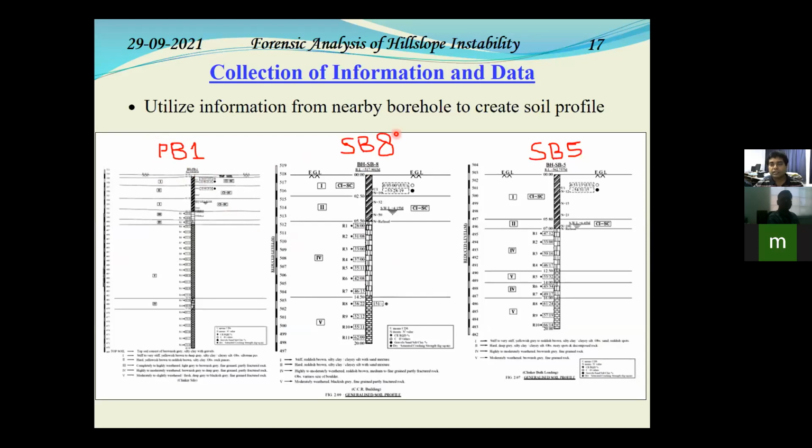What we tried to understand from these boreholes was how the soil profiles were changing over the area covered by the 3 boreholes. Then we tried to make an assertion that we would carry out some analysis considering each of the boreholes, and from each borehole we would consider some soil stratigraphy. Then we would do some preliminary analysis to see how similar or how dissimilar we are from the field observations.